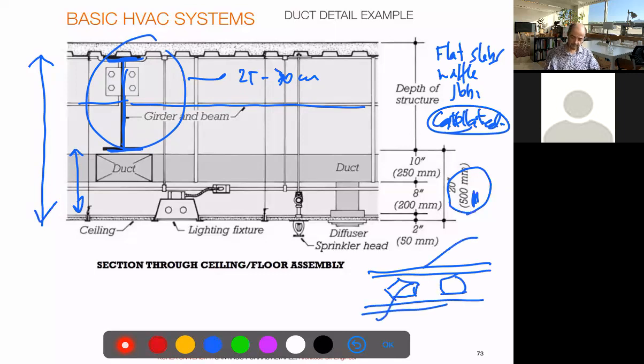So if this beam has some opening, we could have this duct not so on the bottom, but much higher, and we are within the space. There are strategies, but the fact is that most engineers, especially here in Korea, use this kind of beam and girder system, and you're wasting something between 50 centimeters to almost 1 meter